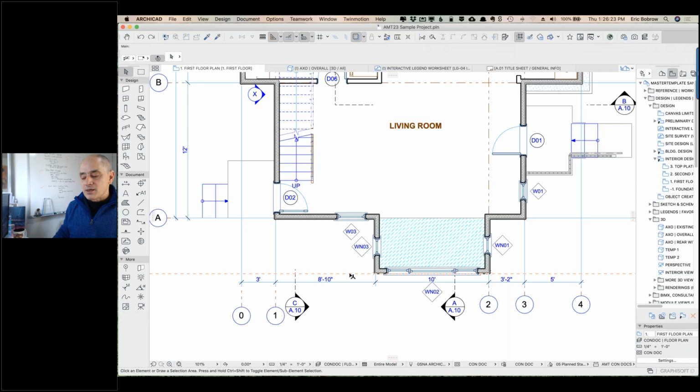Now I can drag a guideline if I hover over it and go to its handle. So then I can move this, and I can move it a specific distance. In this case, I didn't pay attention to the distance. Let me just put it back to the edge. So if I go and grab this, and you can see the tracker is showing a distance, and I can just type in the letter D for distance, or R for the radius would also work, and then type in a value, say 5 feet. And that is going to be an offset 5 feet away from where I started, which I believe was the surface of that wall there.